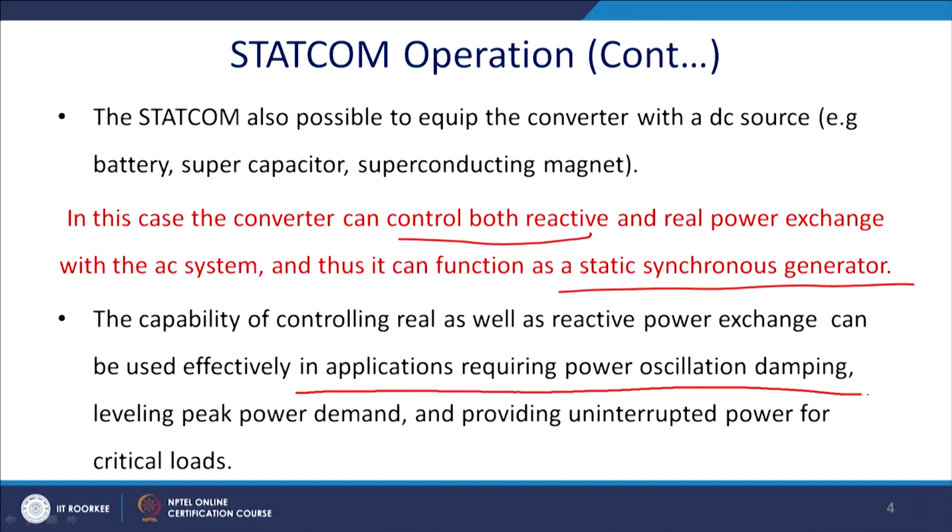The capability of controlling the real power as well as the reactive power exchange can be used effectively in applications requiring power oscillation damping. We have discussed how power oscillation damping can be achieved by SVC. The same thing can be done with the Statcom, and it is more effective in damping, leveling peak power demand and providing uninterrupted power to the critical load. These are the advantages of it.